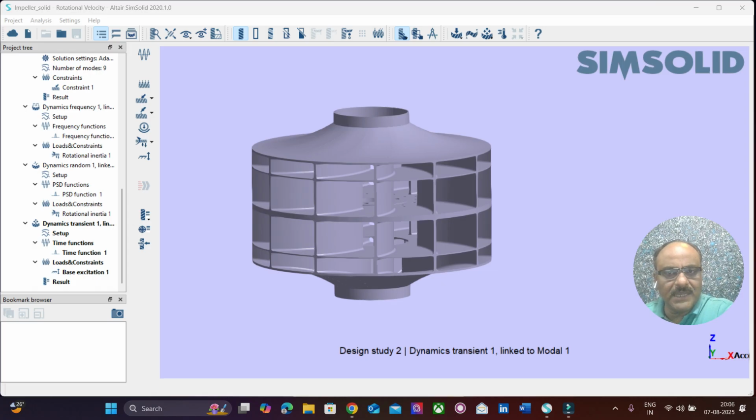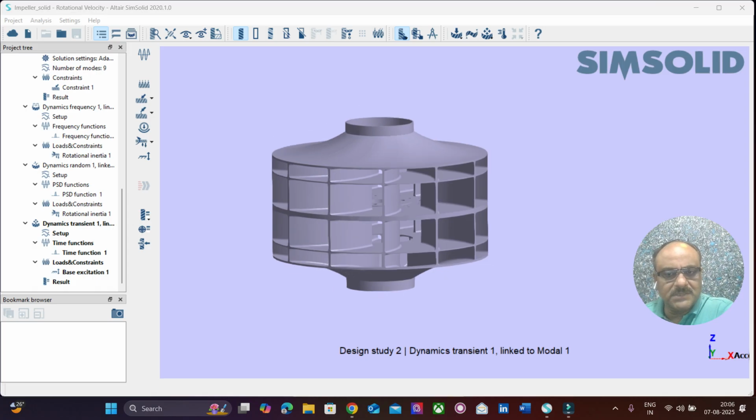So the original casted impeller was reconstructed using a CAD software, and from the basic simulations there were a few optimization iterations done on the structure, and thus the thicknesses and the other related geometrical parameters were changed, and then we found out the deformations.